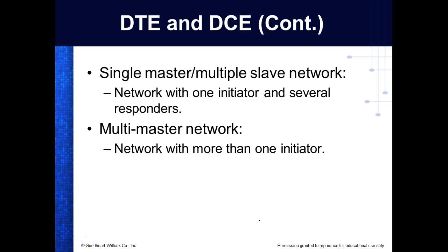So a multi-master network would just mean you have more than one PLC that's designated as a master. Does that make sense? Usually, on a master slave, anything your other PLCs need to access that's not put in their memory, it would access it from the master.